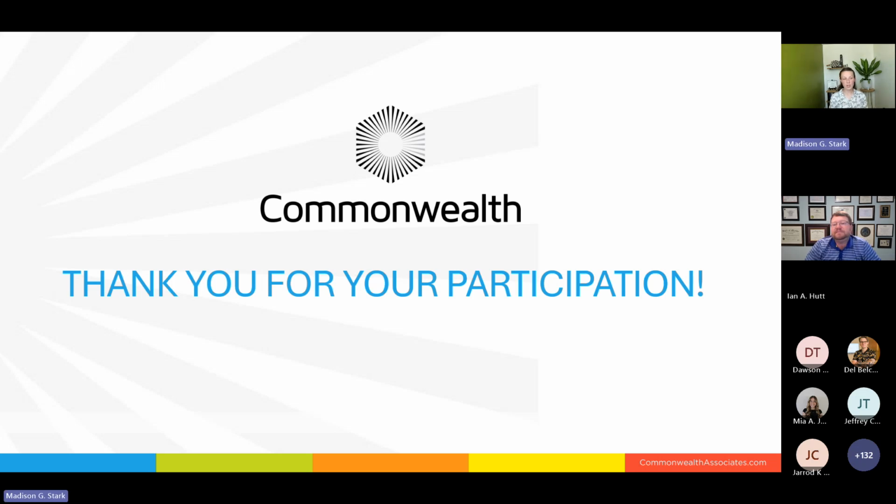Yeah, so when I talked about this, I touched on it very briefly. If your tested X/R is lower than the X/R you see at the site, then you're going to have to derate the interrupting capability of your breaker. So if your breaker is rated at 63 kA, I'm not 100% sure what the math is behind it, but I would assume that either the manufacturer has a derating curve available, or it's available in a regulation or standard practice for deratings.